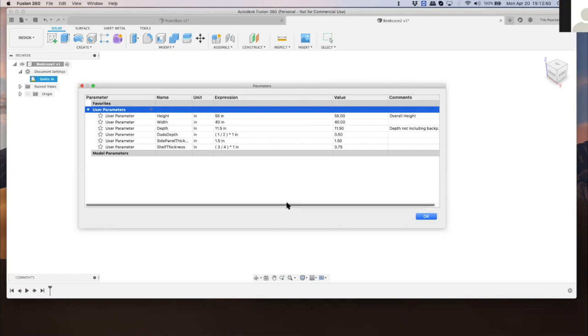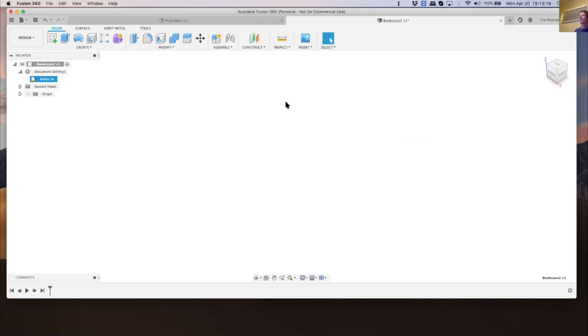Now you can do a few other things in here. Like the formula in the expression column can involve existing parameters. Yes, I had seen that, like the depth being dependent upon the height or the width type of thing. Yes, right. Exactly. So you can use that when you're entering dimensions, and you can use it here in this table as well. Got it. Okay,